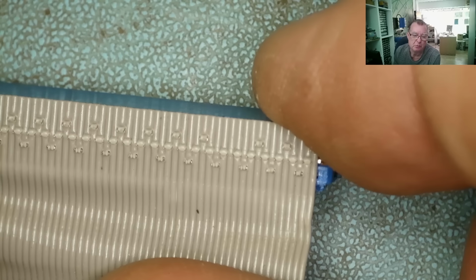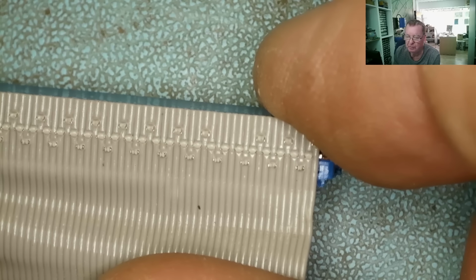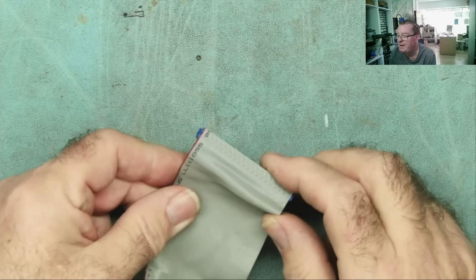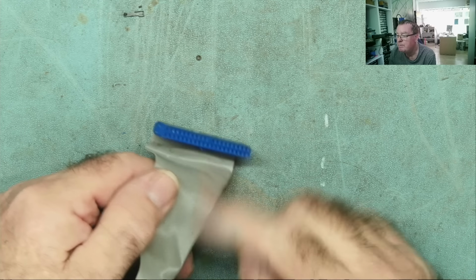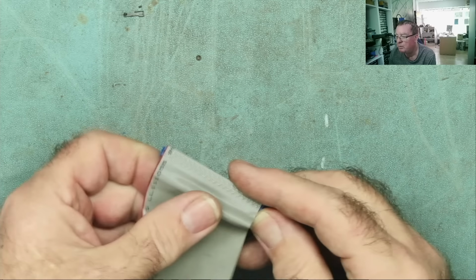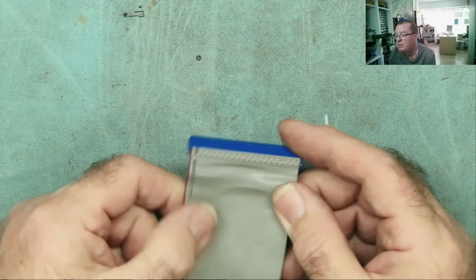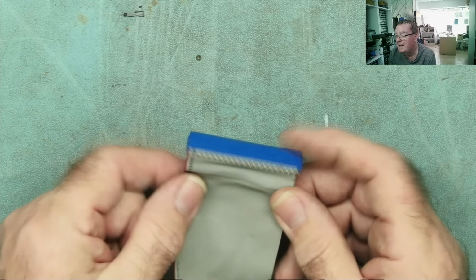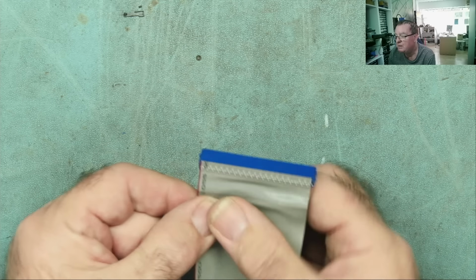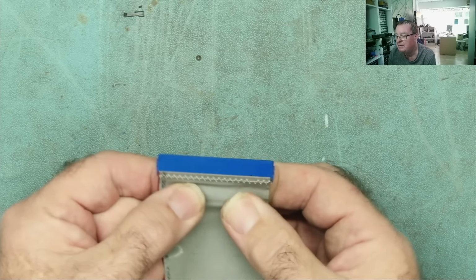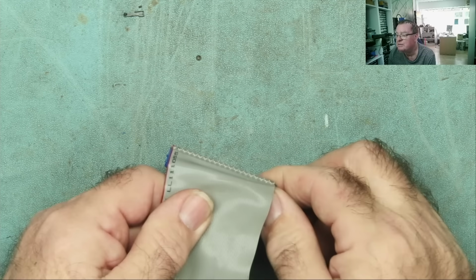As well as computer cables like this, we'll quite commonly find these on audio amplifiers and mixers. In the case of these failing, you can meter through and find the bad one, but most likely the only way to fix it is actually to replace the ribbon cable. Or if you can get another connector and there's enough space, just cut this off and clamp it a little bit further back. Okay, so those are IDC connectors.